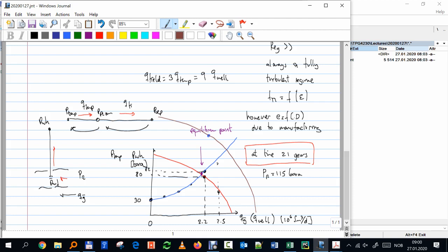And if I want to produce that rate, then these two points at this particular time, let's call this curve time 10 years, the pressure is not the same. The blue one is upstream of the choke and one is downstream of the choke, and the choke is in between. So these two pressures don't have to be the same, but the choke has to bridge this pressure difference. That is the delta P of the choke.